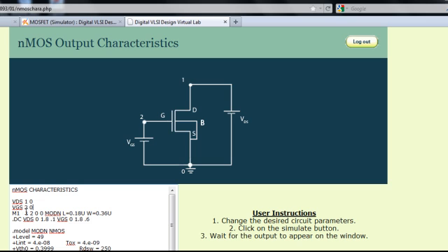The third line corresponds to the NMOS device in the setup, which is labeled as M1 with its terminal drain connected to node 1, gate connected to node 2, source and bulk terminals connected to node 0. One can also define the length of the device and the width of the device as shown here as 0.18 micrometer and 0.36 micrometer respectively.